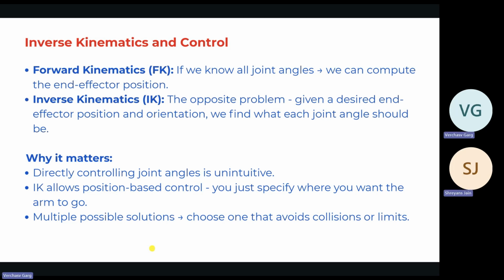So I have this situation there. Okay. Then let me just give you C, right? C would actually come out to be X squared plus Y squared minus L1 squared minus L2 squared, over 2 L1 L2. Right? I'm going to give you this and I hope you will work it out. If you don't work it out, go with it.